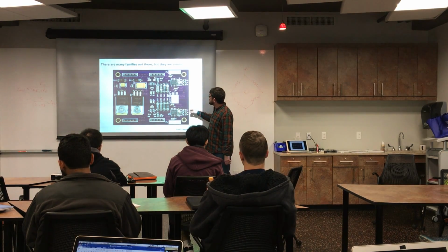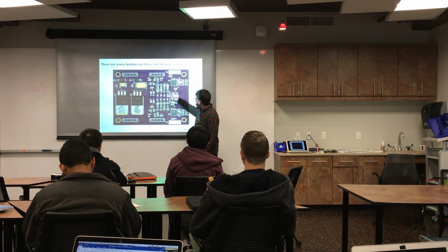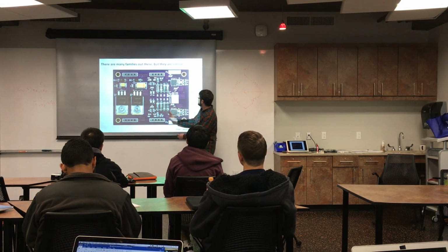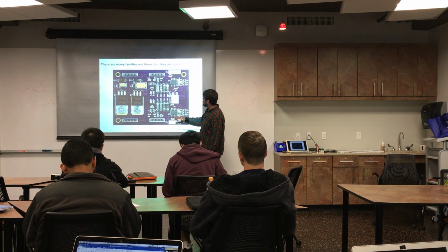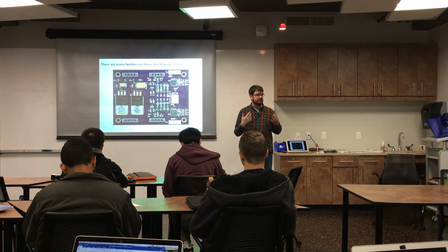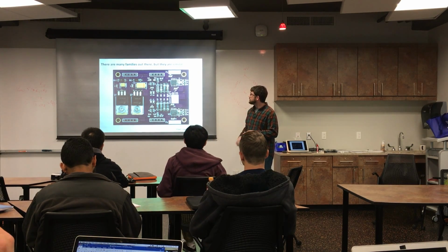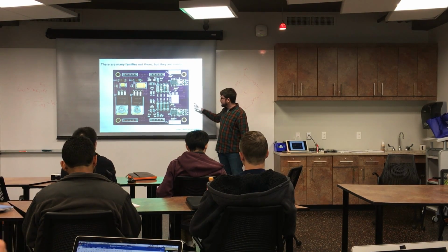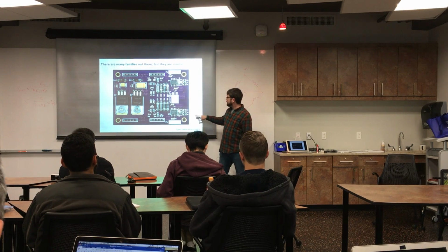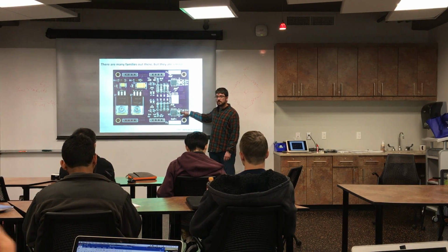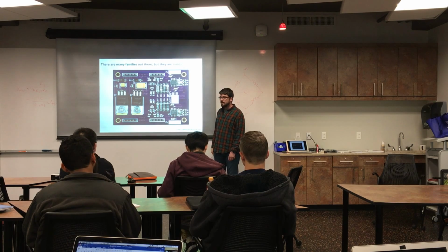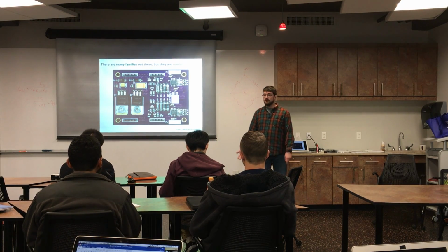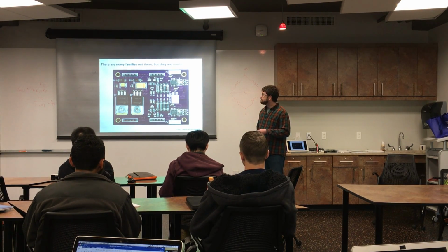This is a board that I designed a while back, and there are two instrumentation amplifiers on it and some voltage regulators and other stuff. But really, this is all that's necessary to make this work. The idea is you put in a differential signal, say your strain gauges or DC-DT, and you select what amplification you want with one resistor. So here there are three resistors, and you select which one you want by how you solder this together. And you have a really nice low noise differential amplifier that has a single-ended output.